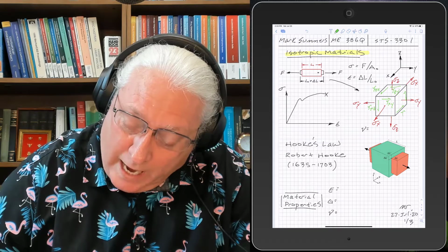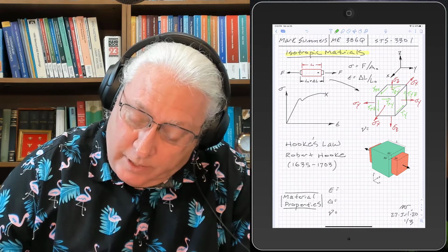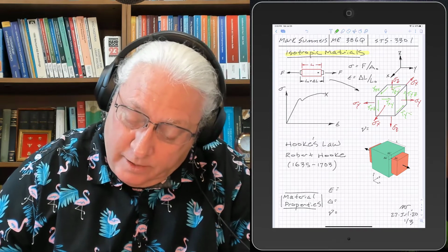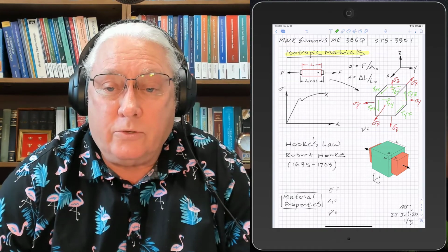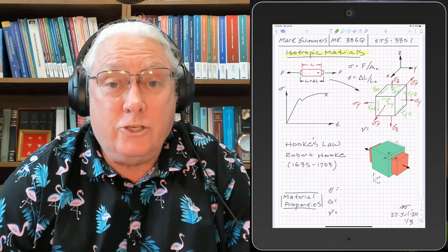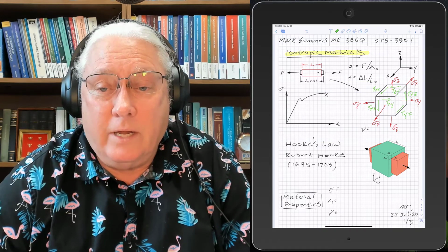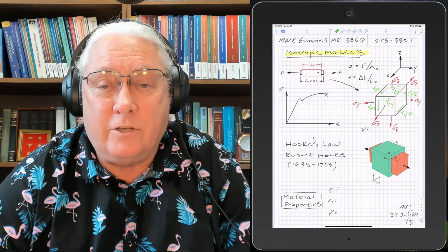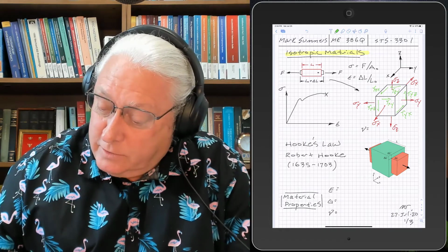So this is tau y. This is the y face. This one's tau y in the z direction, and this one is in the x direction. So I've got 3 normal stresses. It's a general case for loads in all different directions. I'll have 3 different normal stresses and 6 different shear stresses on my stress element. Okay, so we've got that defined.